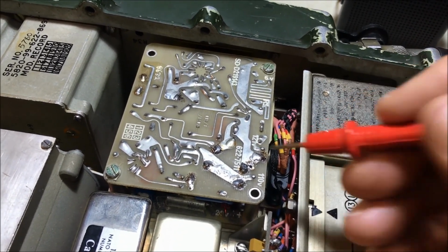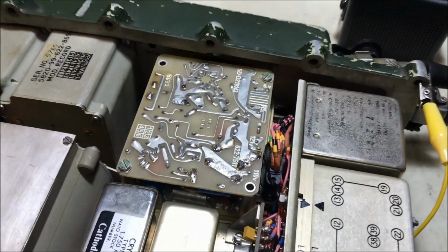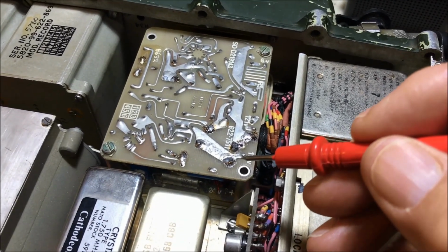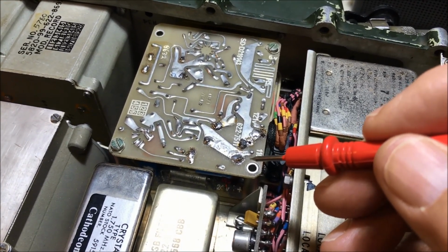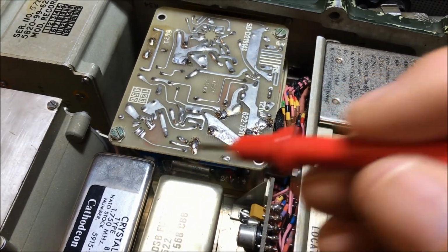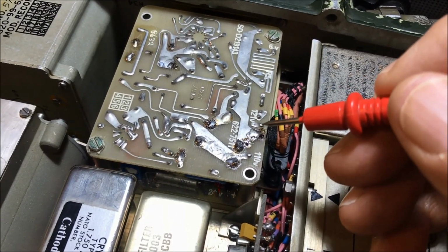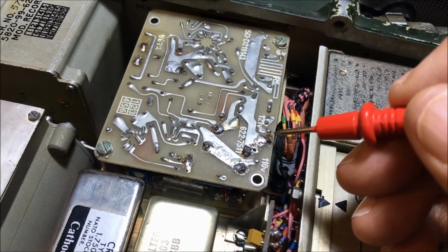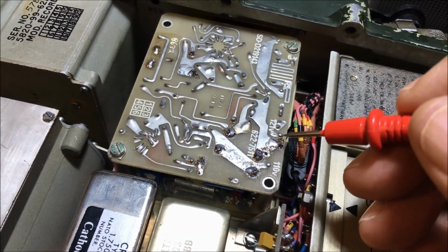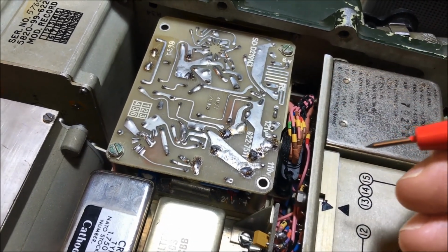We need 121 volts on the unregulated side to get 110 on the regulated side. So if you measure your power supply after you've done the upgrade and you want to adjust it, I think there's a potentiometer down here underneath there that you adjust to set the 110 volts. But you actually need 121 on the unregulated side to get that 110 volts. So if you're not getting 121 volts there, you need to be looking earlier in the power supply, on the other side of the little transformer.